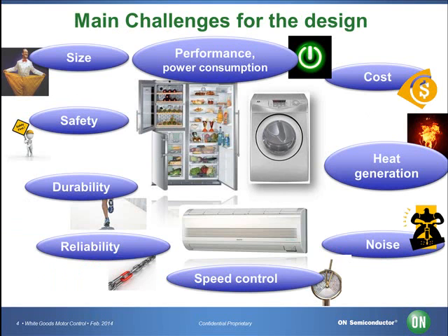What are the common challenges that an engineer would face? Along with the trend for green power applications, a low power and highly efficient device is required for motor driver ICs. The engineer would look for motor drivers providing the best efficiency for the most amount of cooling required. If the fan driver board is inside the main compartment, heat is generated by the components and extra power is required to compensate. Low noise is very important for the homeowner.